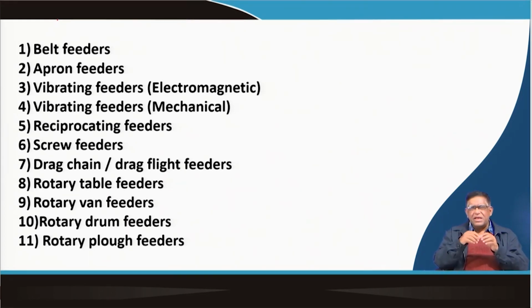But mechanically, you have a shaft, and a plate on that. Below, you keep a shaft on which you keep some different diameters. So, a different rate of pulsations will be coming, and the system will be vibrating. At the bottom you will have some spring systems, and because of the spring system the vibrations will be coming up over there. So, that is how you can give vibrations mechanically. You can keep something on an incline, with the spring in front, and when the load comes, it will start giving a reciprocating type of vibration, and the material will be moving forward. There are different things available, and you can also think differently.